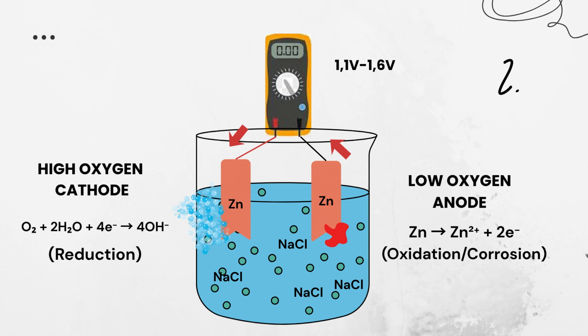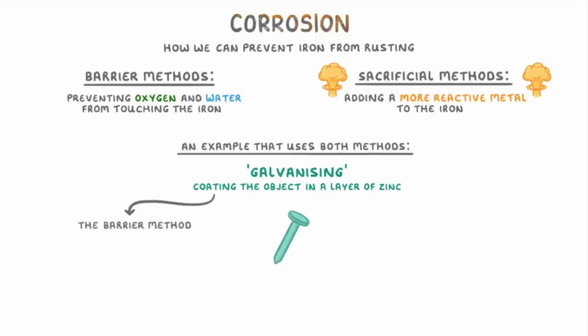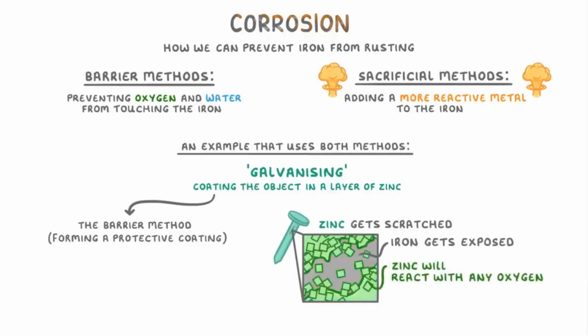Electrochemical process: oxygen gains electrons and forms hydroxide ions, so that region doesn't corrode. Zinc loses electrons and forms Zn2+ ions, and this is the corroding area. An increase in voltage between the plates shows that an electrochemical cell has formed due to the oxygen concentration difference. Final result: the plate with bubbling is protected, while the one without bubbling oxidizes more quickly.